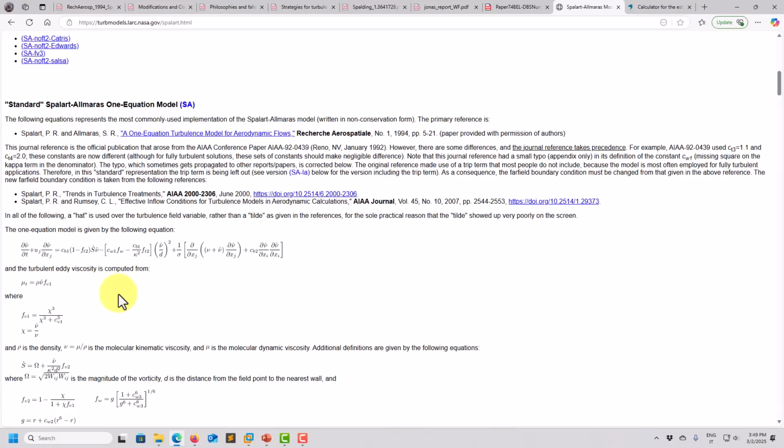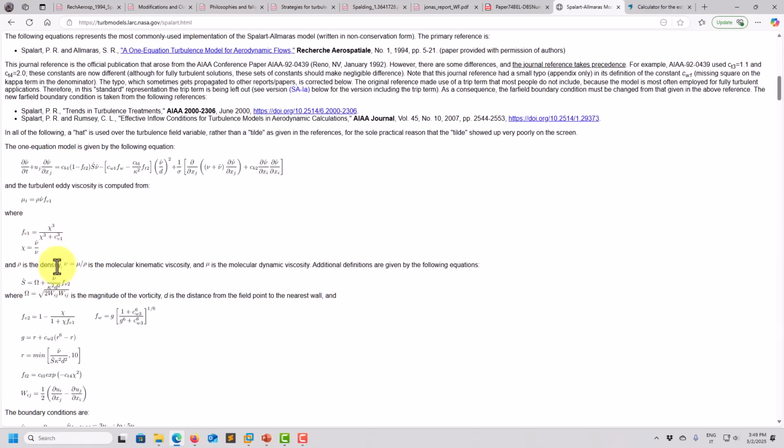In this model, we introduce the modified viscosity to compute the turbulent viscosity. This modified viscosity has the same units, and our goal is just to get that. Look at the turbulent viscosity, computed like this. You then have this blended function that will do its job. Then this model is also introducing in some way vorticity. You have this quantity here, the vorticity tensor, then you have many more functions.